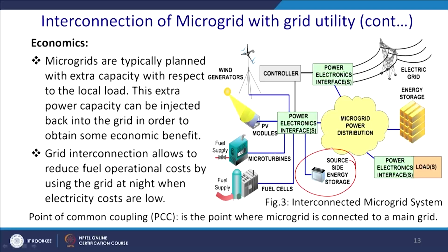Through that it is an active power rectifier generally, or filtered, depending on the bidirectional power flow from the grid to the microgrid and vice versa, and you may have a bulk energy storage to exchange the power, and power electronics load interface can be done by it. So, this is an interconnected microgrid system.